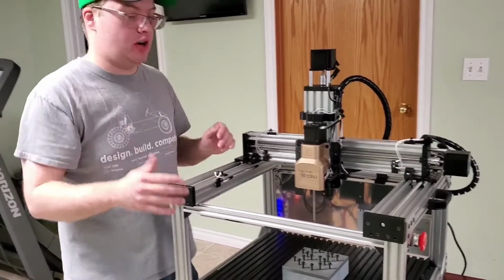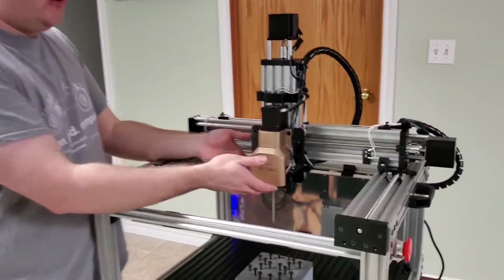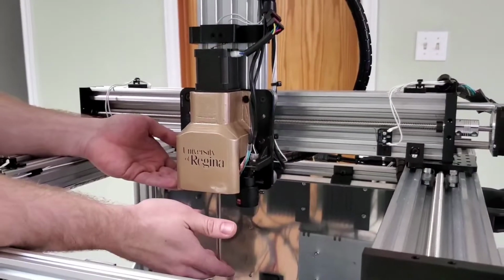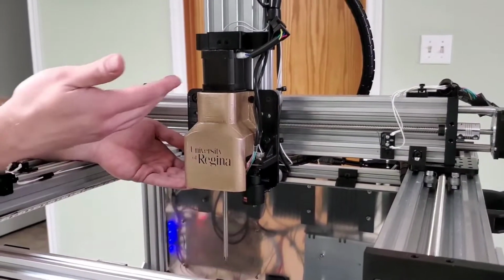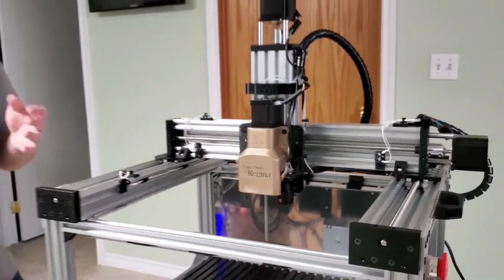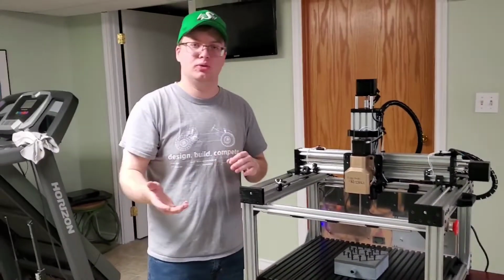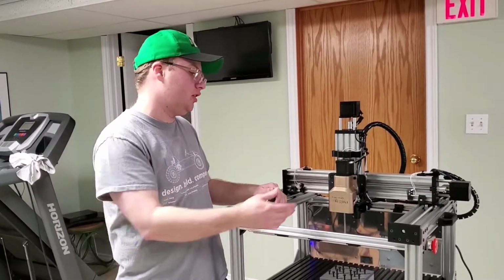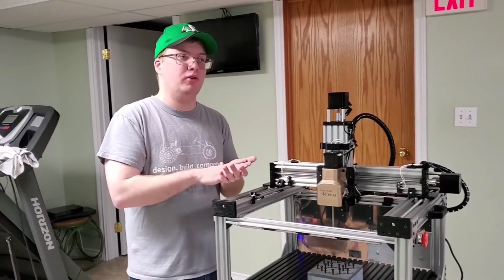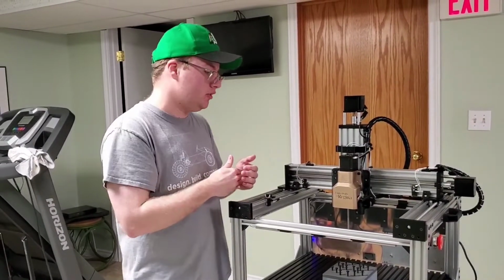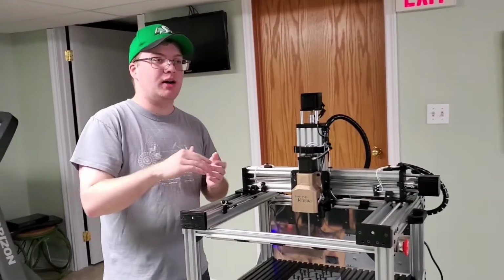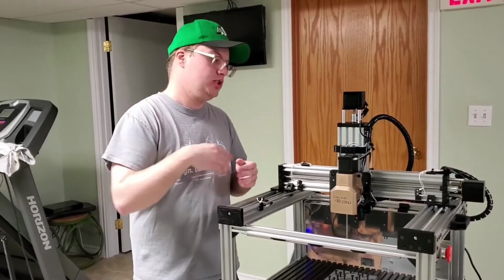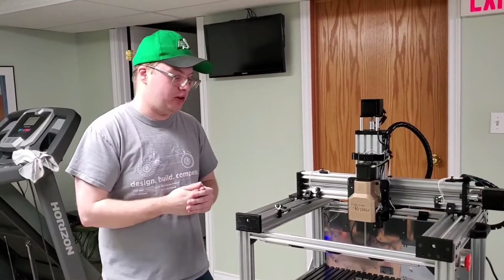Now, there's a few things going on with the mechanical. Starting with the screwdriver module, when we contact a screw, we're going to move upwards until we've engaged this limit switch. So this gives us a reasonable amount of force, between 15 and 30 newtons of force onto the screwdriver, which is in the expected range of a screwdriver. This is essential, obviously, for applying force so we're not slipping within the screw itself. As well, this travel allows us to move up and down while we screw in a screw or screw out a screw. So it gives us some natural travel that you would have with a human.